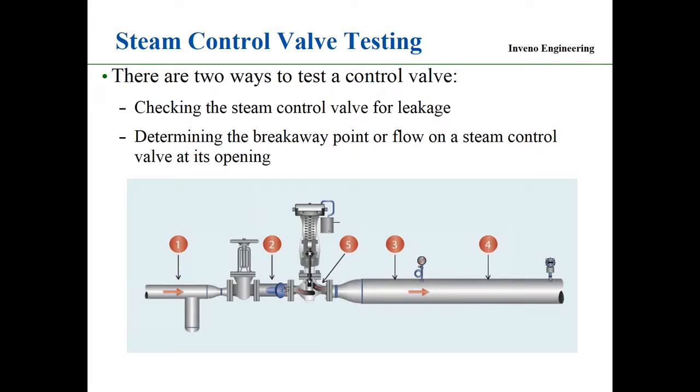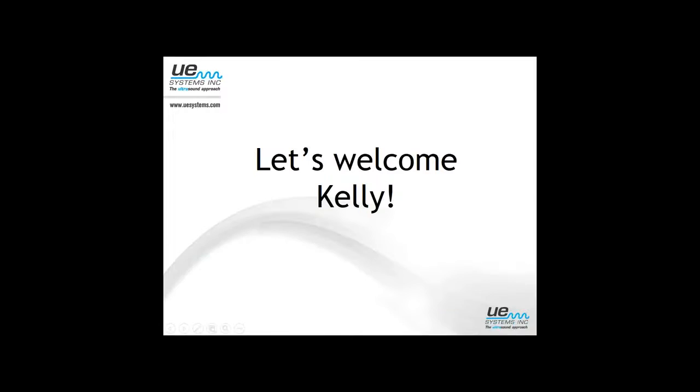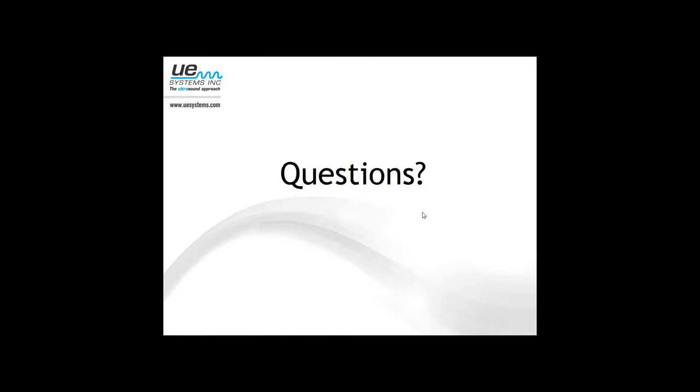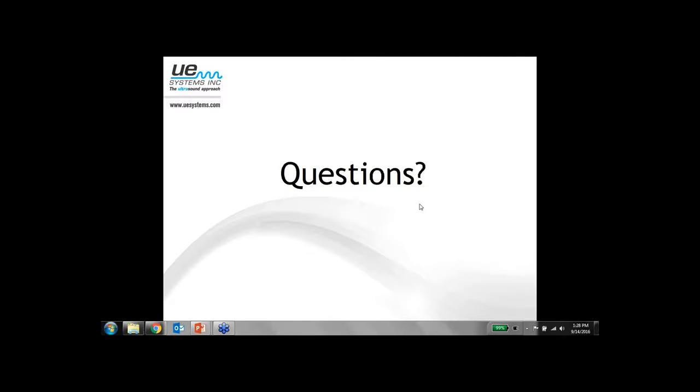And then this other person asks, if valves and steam traps are surrounded by insulation, how do you test them with ultrasound? Again, if insulation is a factor, if it's permanent insulation, make a test port where the stethoscope module will go through and make contact with the pipe. Once the test is done, plug that port, which gives you access from that day forward: go up, look for the plug in the insulation, remove it, and then the probe can go in, which is done all the time.